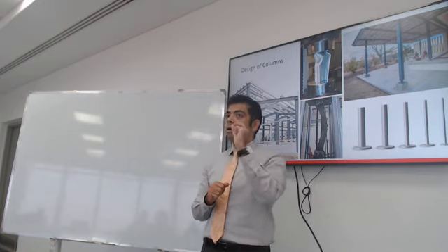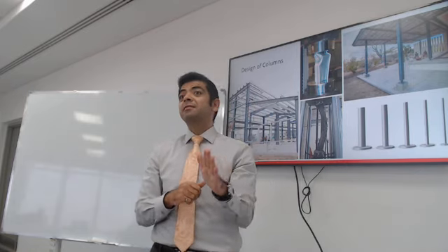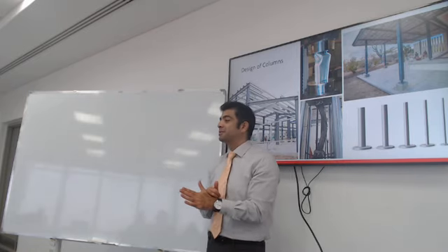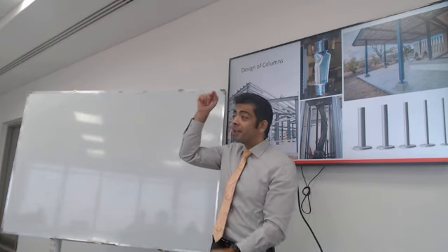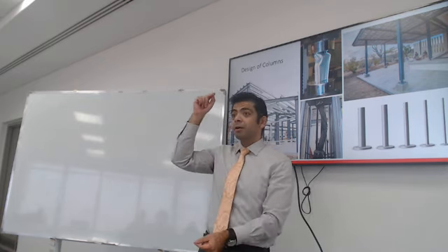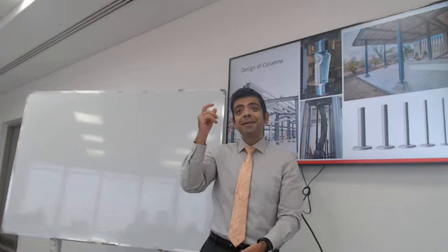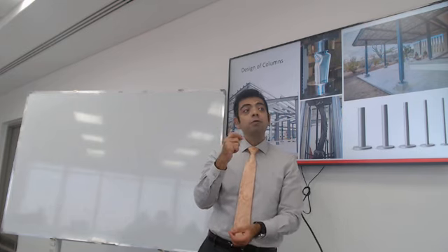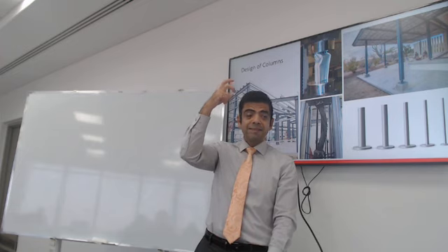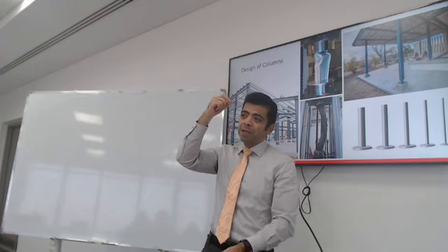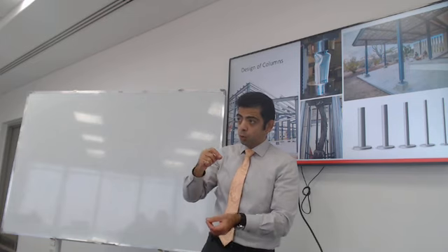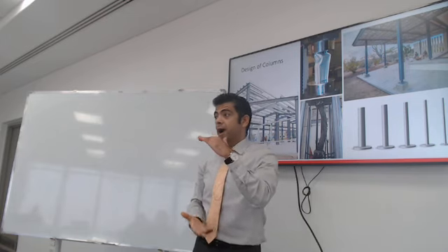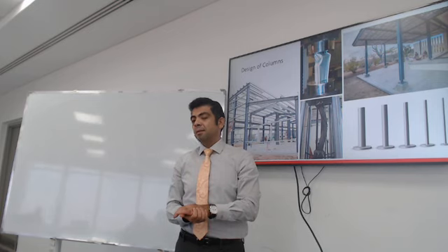There is one main decisive factor in the capacity of a column. Simply span? What's that? The length. Yes, the length of the column will make or break the capacity of the column. Super tall and slender columns are weak and flimsy, and they have small axial capacity. Short and stiff columns have very high axial capacity.